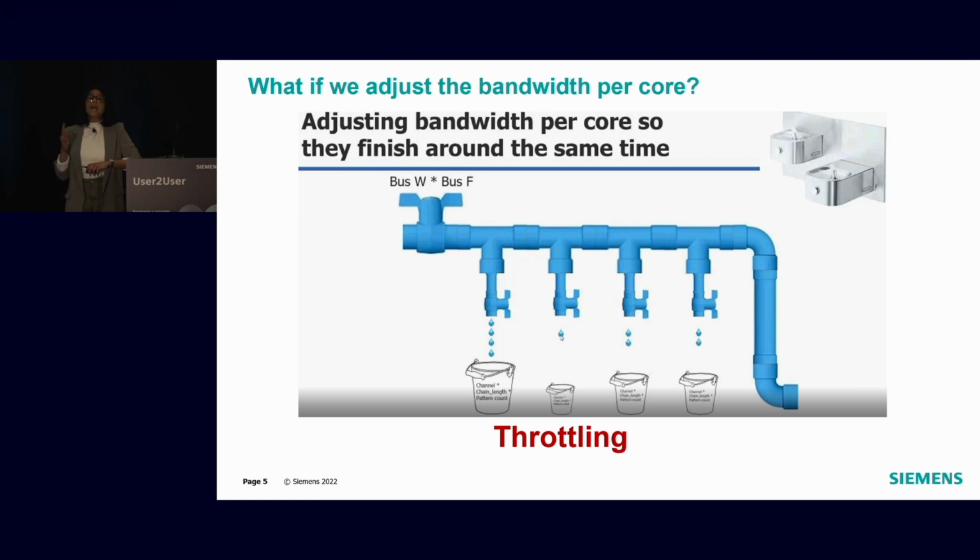Now, how do I control how many drops go in a bucket? And that's where the magic of the tool lies. This factor, which controls how many drops are going to fall in each of these buckets, where drops are the bits being delivered to your core under test through the packet, and the bucket really is the core under test, I will call it throttle level for the rest of my presentation.